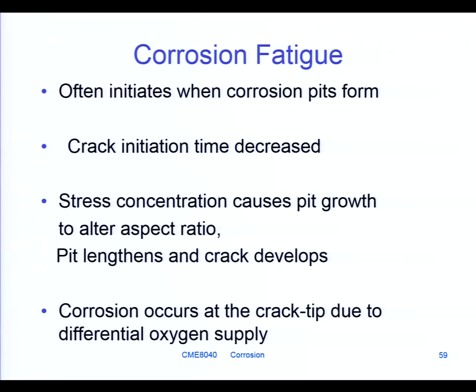There is undoubtedly lots of evidence that you get stress corrosion cracks without any pits forming first, and there's also situations where you get pits formed and then you get stress corrosion cracks from them. That's quite easy to observe, and partially that's because the cracks tend to be pretty hairline, pretty thin cracks. In corrosion fatigue, it's a bit more difficult to decide. There's a lot more corrosion and mess in the samples, I would say,